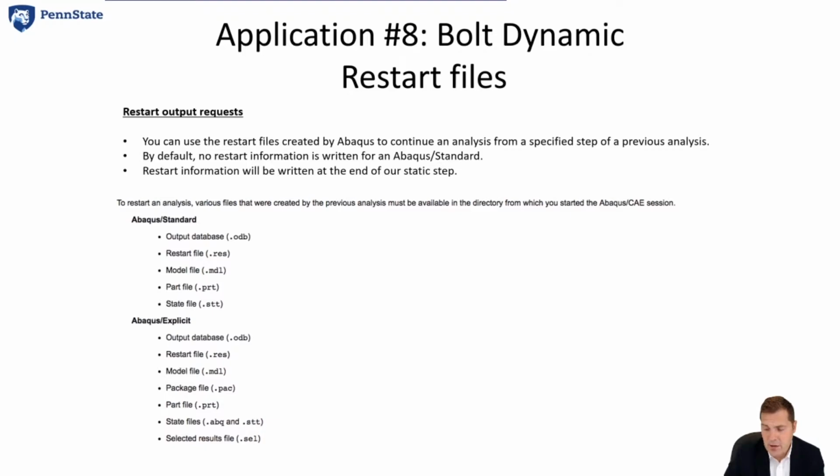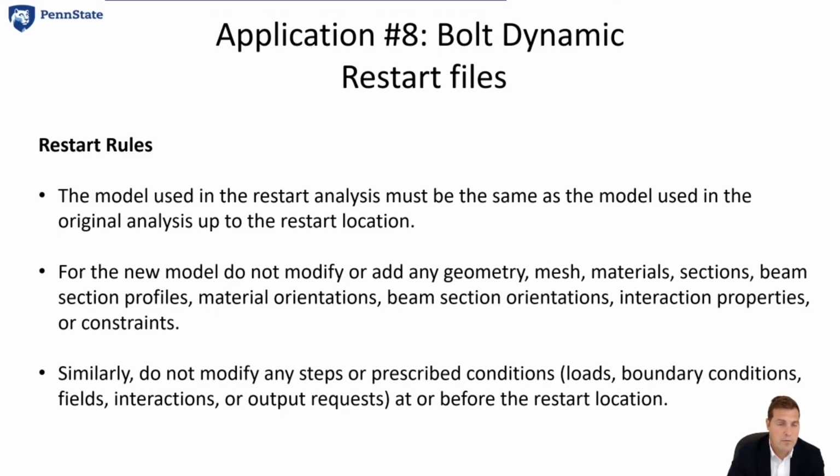And then the other thing it's used for is when you have a dynamic simulation that is maybe going unstable. You can set the frequency such that it writes out every 100 steps or something. And so you have a spot where it'll pick up from if your simulation crashes. Okay, it's another useful use of restart files.